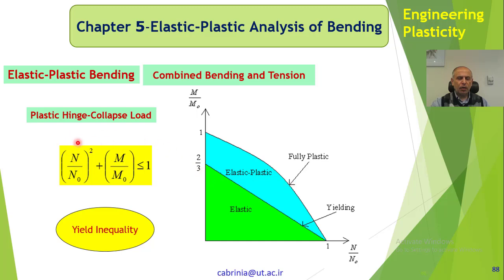All of them, we have used this yield inequality in here to obtain this value. So this yield inequality could be of some use in other problems as well. In similar problems, you can obtain the yield inequality, and you can draw such a graph to see where the points are that you can load the geometry or whatever you have. What are the points that are elastic, what are the points that are elastic plastic, at which point it yields, and at which points it becomes completely or fully plastic.